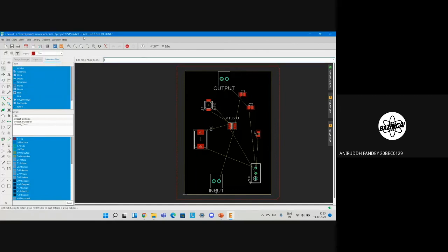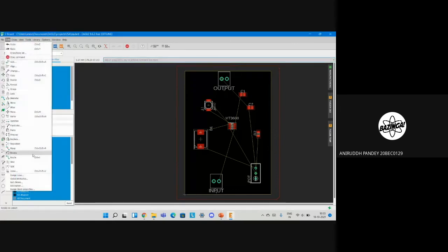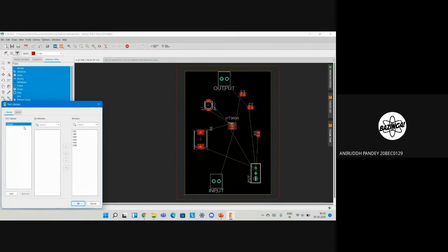So you can just go to mm. Now, if you want the auto routing, net classes define the rules. Say let's say 12 mil drill. Drill is for the via. If you're connecting the top and the bottom layer, what's going to be the size of the hole that you're going to drill? So let's say 10 clearance. Clearance is the minimum distance that's going to be between two traces. You've got to have a minimum distance so that the signals don't interfere.